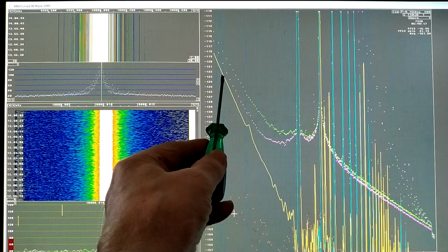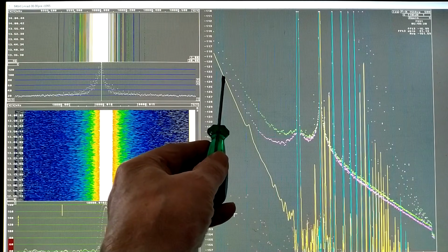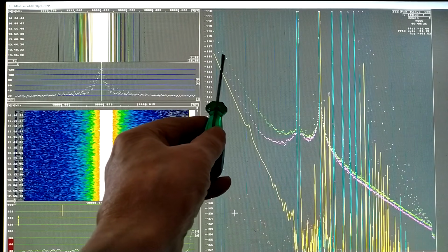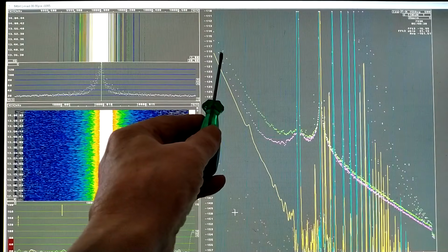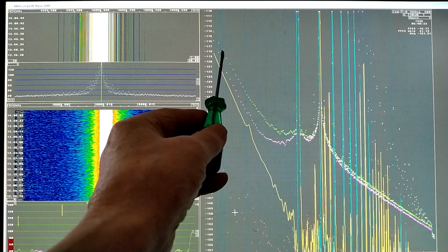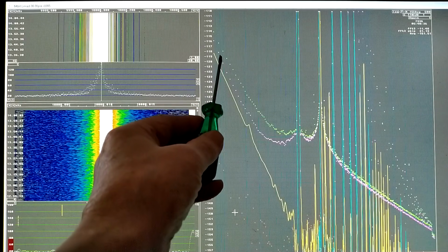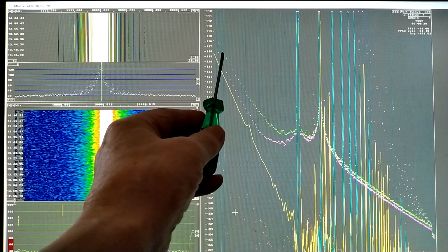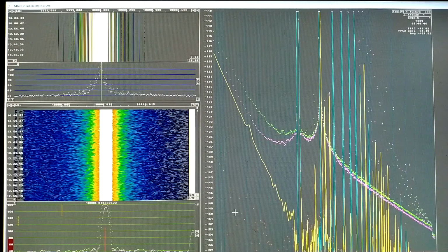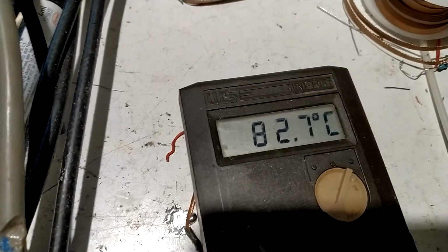The Wenzel oscillator is at minus 120, but I read minus 118.3 or so, because that's the sum of the noise, minus 122.8 and 120 becomes minus 118 point something. I'm not doing the math properly, but it seems to fit pretty well.